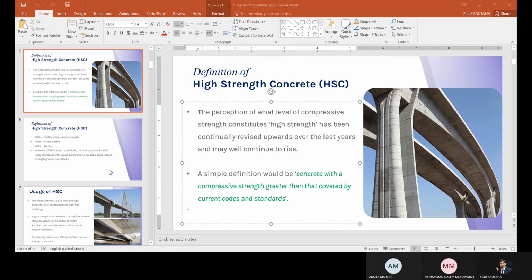The maximum size, the high maximum size. I have two mixes again. The first and second have the same mix proportions, same mix design, same ratio for the materials, but they only differ by the particle size of aggregates. The first mix has aggregate ranging between 4 up to 14 millimeters. The second mix uses aggregate ranging between 4 up to 20 millimeters.